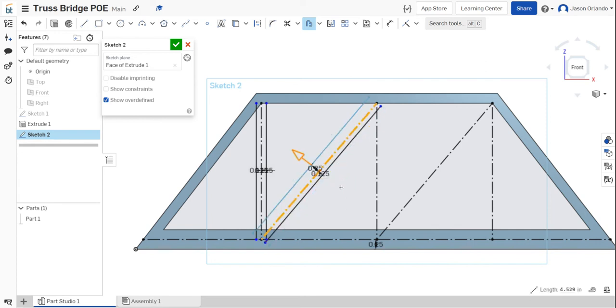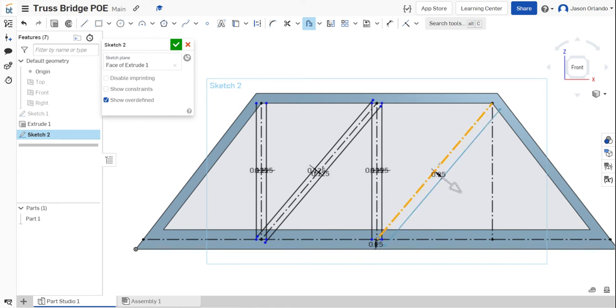Endpoints, kind of a pattern to clicking. So I guess it's click. If the direction's good, I hit enter, and then I can type my new dimension. If I click on the center line and I don't like the direction it went on the side, I click the arrow, and then I hit enter, and then I type again. So it's click, enter, update dimension, or click, adjust direction, enter, edit dimension.